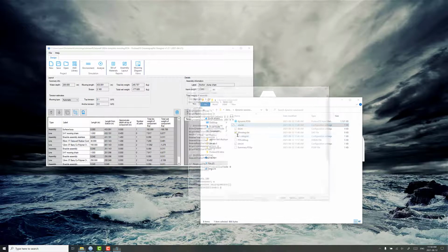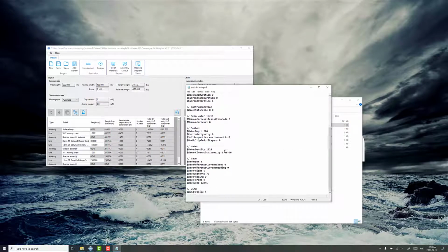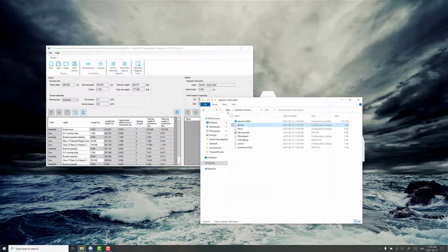but be aware that you can actually edit these files. They're just text files. I don't always recommend this if you're not comfortable with it. Don't do it. But you can change the wave seed pretty quickly this way. And this number, it just has to be an integer. As long as it's different than the other numbers, it'll give you a totally different representation of that time series. So maybe you just do 1111. We'll save that. That's a different seed, wave seed 2.